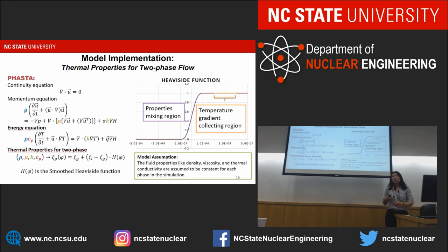So in order to conduct boiling simulations, the first thing we need to do is to modify the code to include the energy equation in the liquid solution. And also the thermal properties for two-phase are smoothed using the same approach, like Heaviside functions to smooth across the interface.